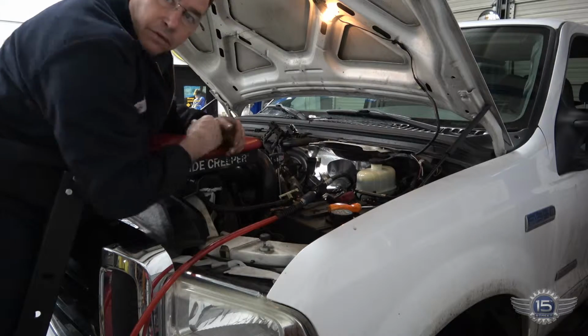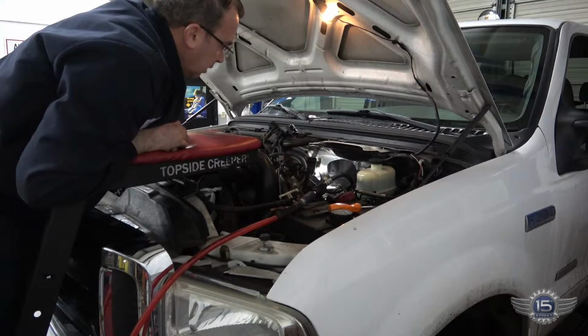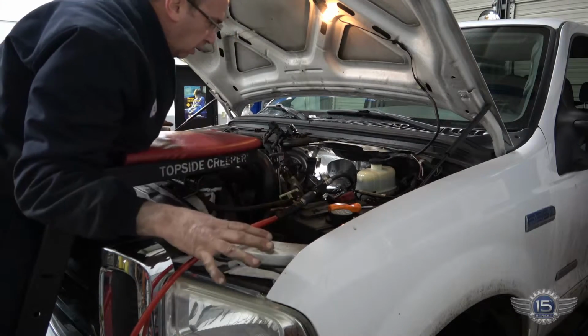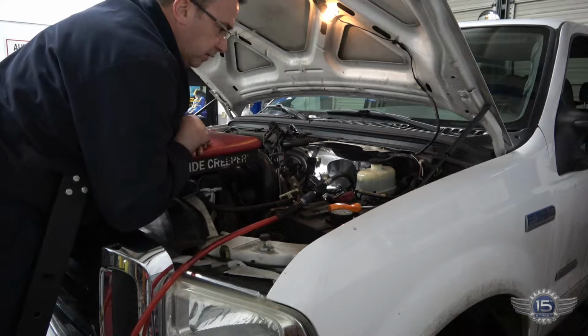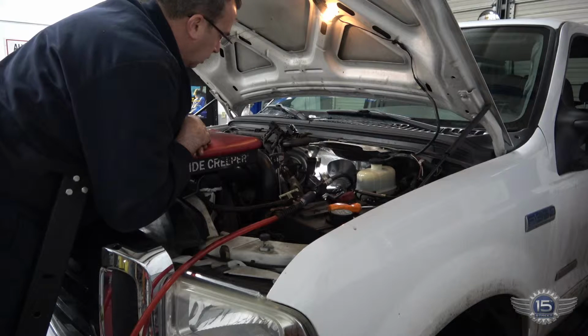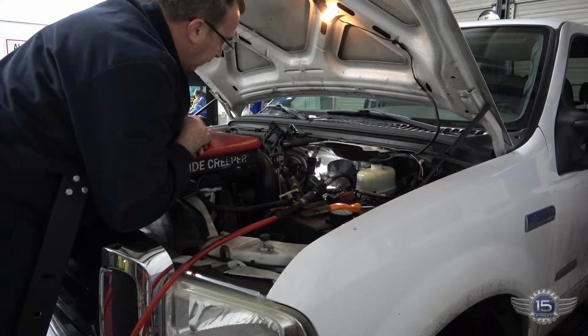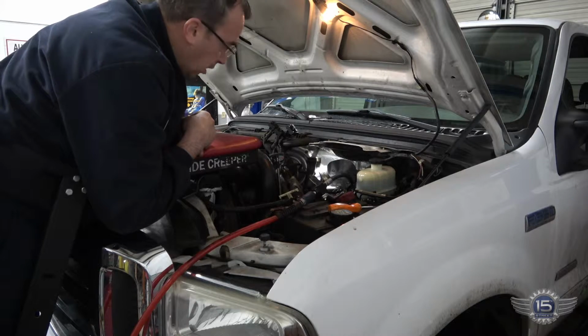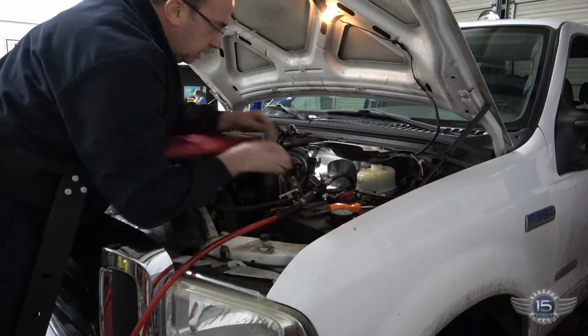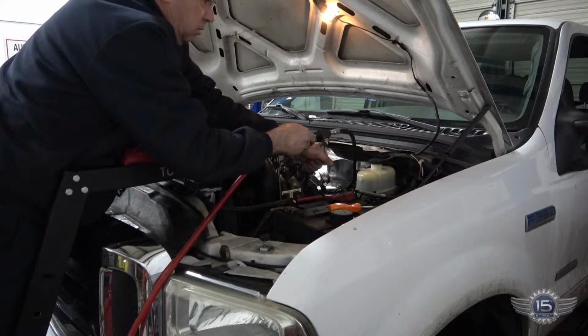So we let it sit here for a few minutes. It'll blow the oil out of the high pressure oil system, and then an air leak will develop. But I'm not hearing anything. So it's holding pressure. If it can't produce pressure and it's holding pressure, it's either a bad pump or a bad IPR. So let's leave this thing hooked up here.